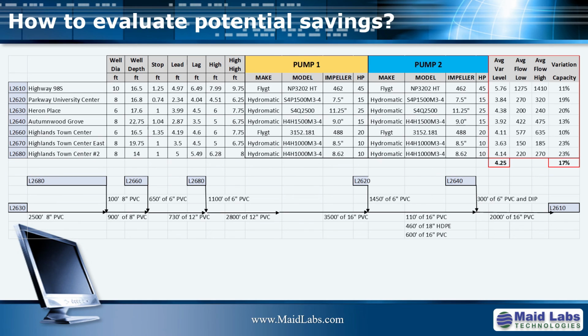We have a test bed in Florida with 7 lift stations where they are analyzing data right now to see how much money they will be saving using a flow-based operating system. In their case, when the flow rate is low, they can increase on average the level of operation of their pumps by 4.25 feet. In their case, the average increase in pump capacity because of the change of head is 17%. So increasing the pump capacity means it will reduce the run time by about 34% when the flow rate is low, which is most of the day, by the way.